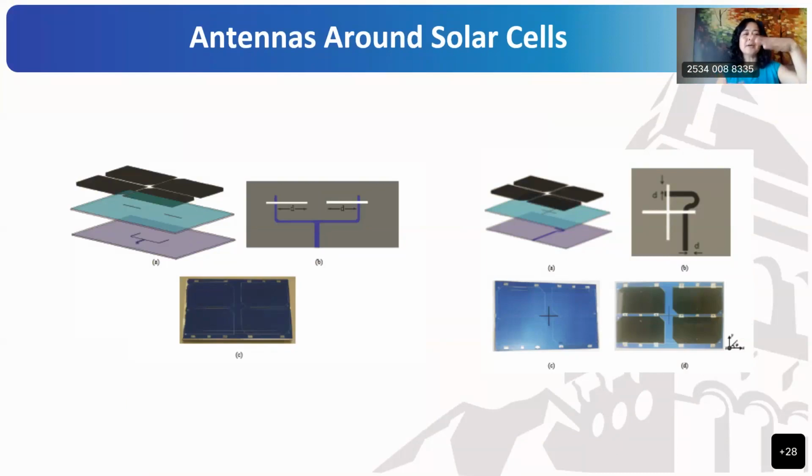As you know, under the solar panel, oftentimes it's a metallic plate or ground, or just the CubeSat frame. So that's metal. As you know, you can't put a dipole antenna very close to the ground, right? Because image cancels radiation. Therefore, what we can do is create a slot. A slot is a negative image of a dipole antenna. So we create a slot and let the slot radiate. That's the design idea here.